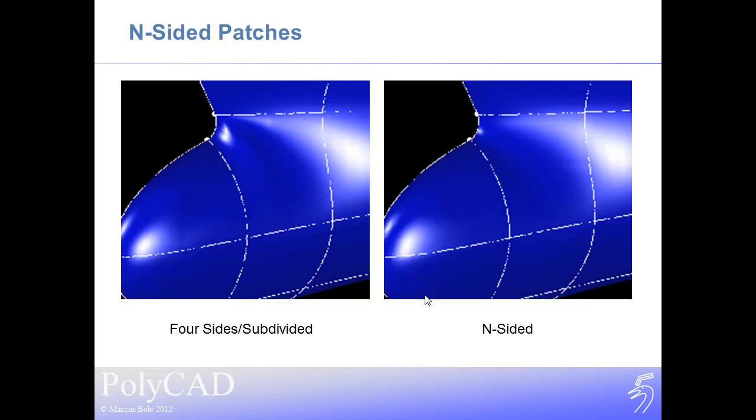of NURBS. So this is a bit of a challenge that we have these other surfaces that can represent these shapes, but we've got to take the limitation that we might not be able to export the exact representation into a file format so it can be used by other CAD systems. So this is the dilemma that the software developer faces when generating this multi-patch hull form representation tool.